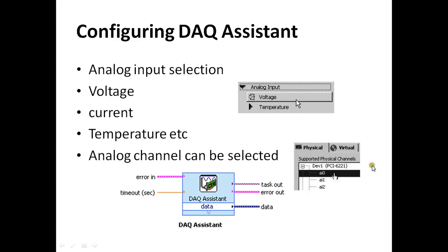All those things we can set in this section. If we are going for analog output, there also we can select which channel we have to get the analog output. Since it is shown here as analog input, we are getting AI0. If we are going for analog output, we will be getting AO0, AO1, like that. And whatever parameters we are going to measure, voltage, current, temperature, whatever we are going to give, we can directly give it here, and we can implement it directly from here itself.